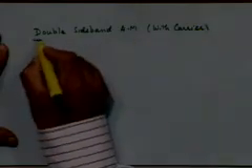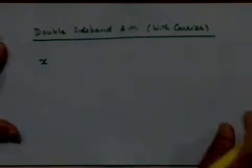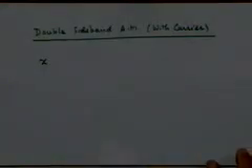So this is no longer suppressed carrier, we also put a carrier component in this. So basically what we are saying is, in fact, when generally one refers to amplitude modulation in practice, one is typically referring to this situation and not the suppressed carrier situation that we have discussed so far. Okay? The suppressed carrier situation is used typically, or was used earlier in the earlier days, typically for transmitting data signals. For voice signals, this is one of the most commonly used form of amplitude modulation.